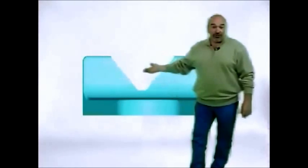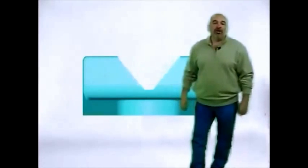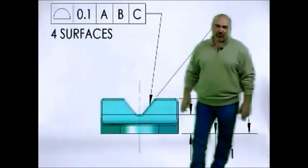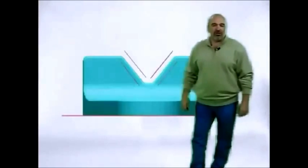The angled surfaces on this part, for instance, need to be located relative to the datum reference frame. If angularity had been applied, the drawing would be incomplete. Profile of a surface locates the surfaces in addition to controlling the angularity. The angled surfaces of the V-block cannot be tipped more than the profile of a surface tolerance of 0.1.